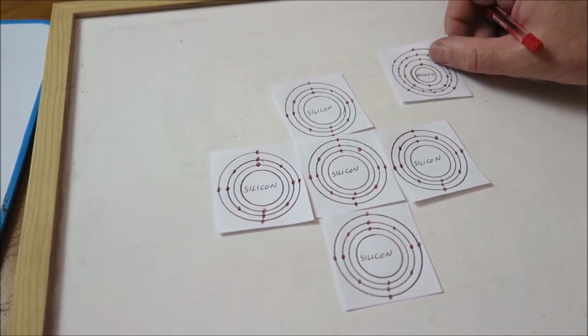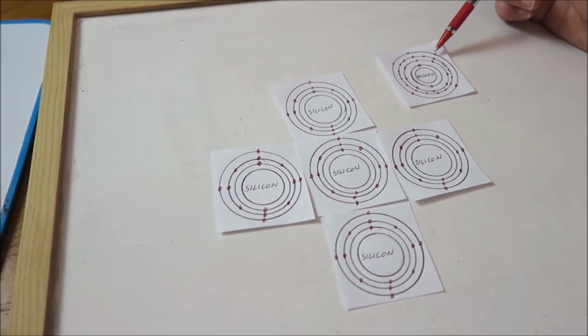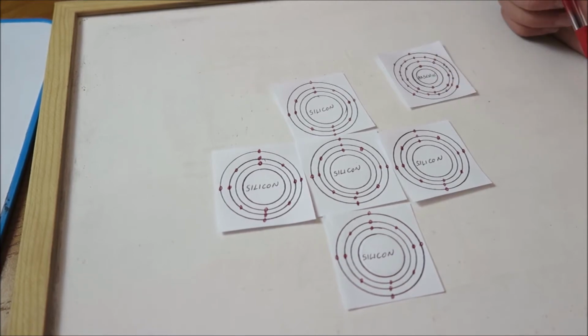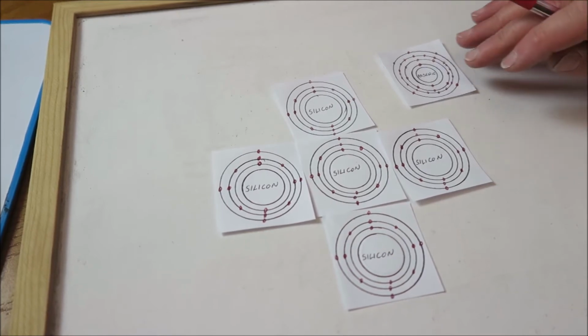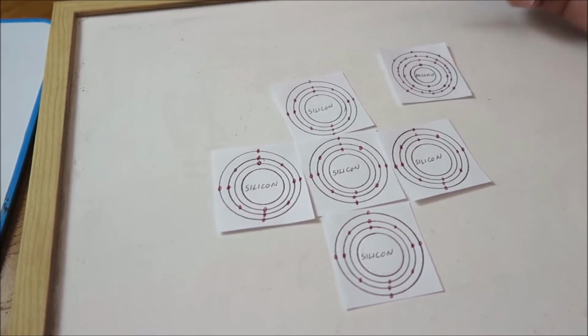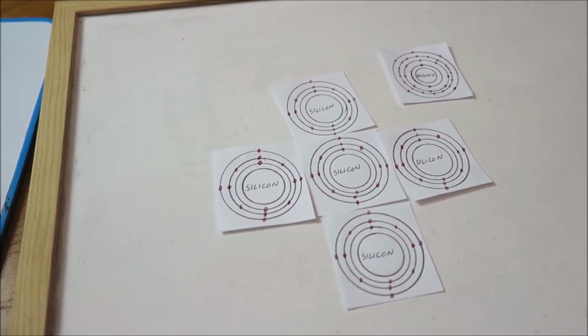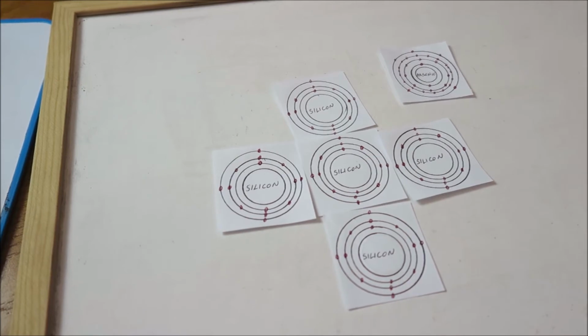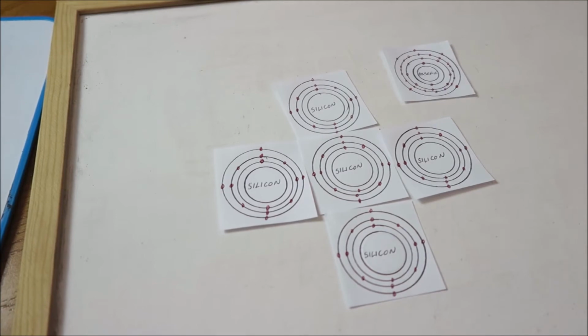You can add something like arsenic to it, and arsenic has 5 electrons in the outer shell. So that's called a pentavalent material. Pent meaning 5. So we can dope the silicon with arsenic or with aluminium or with other trivalent and pentavalent materials to get the silicon to conduct better, to make what is essentially a non-conductor, although it conducts a little bit, into a semiconductor material.